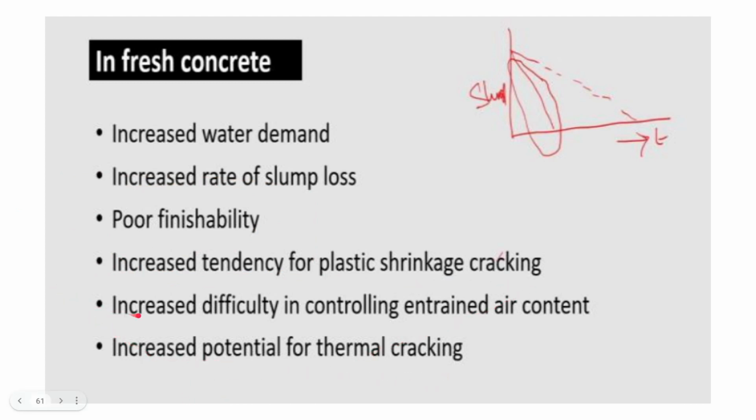And increased difficulty in controlling air entry and air content. Because so many cracks will be developed that we don't need entrainment, it will be entrapped air. So because of cracking, a lot of air content will develop. So these are some of the criteria which affect fresh concrete.